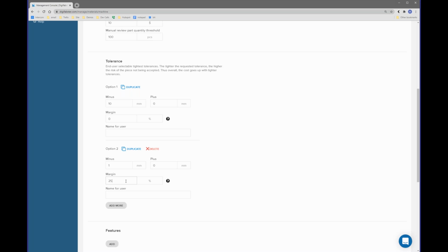Other shops prefer to have a set of base tolerances for their shop. And then what customers can do is they can choose the base tolerance with 1 or 2 advanced features or high tolerance features. This way, again, we can have that baseline set up, but if there's one feature that's very critical to the part, we can have a higher tolerance feature for that one part only.